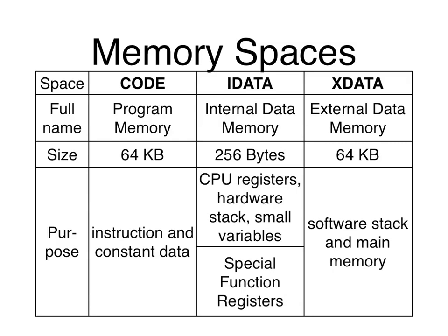Now, I think I mentioned this before. XData is only external to the core or external to the CPU, but oftentimes it's integrated on the same chip. The classical 8051 has a separate XData because memory chips were not easy to integrate back then, but now process technology has improved so much that it's just a tiny little area. So the 64K code and 64K of XData are conceptually separate. Even though they're both 64K, they usually refer to entirely separate locations.